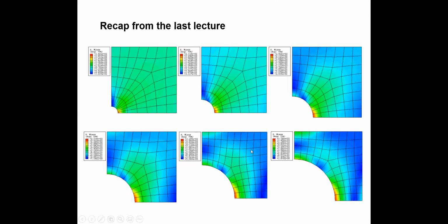You can see this is a thick plate, with holes penetrating to the other side. If you have this kind of stress raiser, you need to use this kind of graph with bending. And if it is an axial load, you need to use this kind of graph. This is when we change the stress raiser radius. If it is a circle, when we change its size, the simulation explains how stress varies.